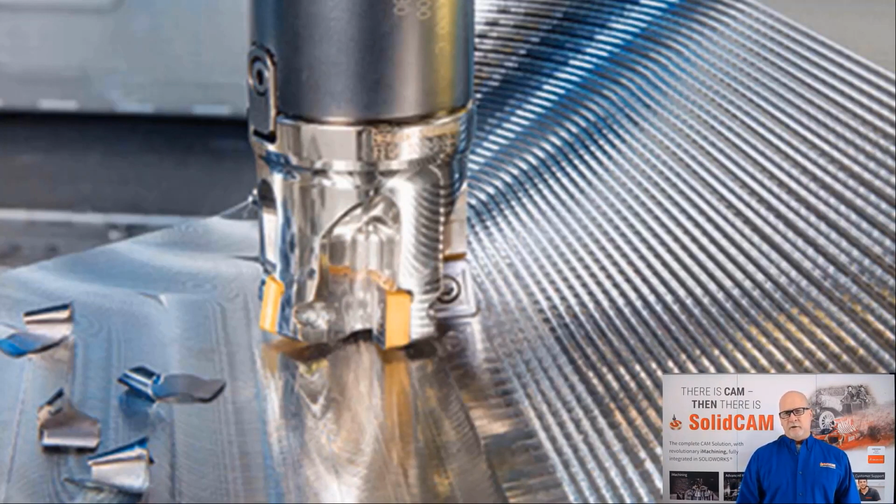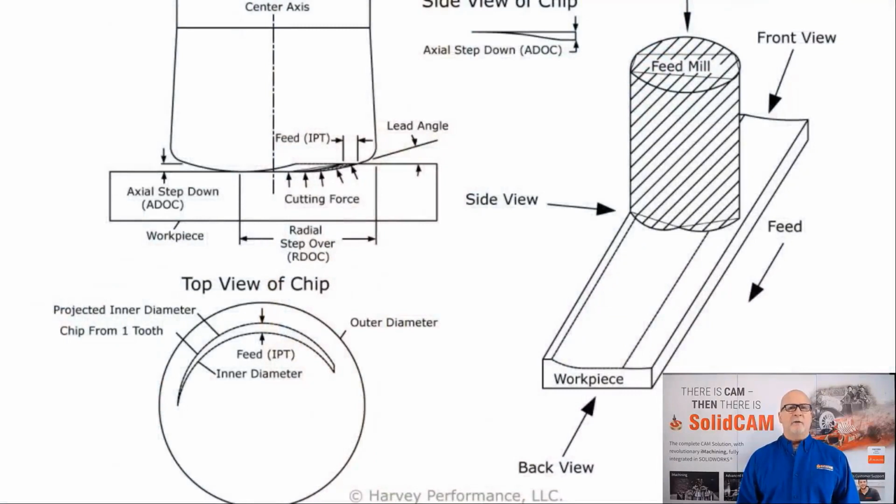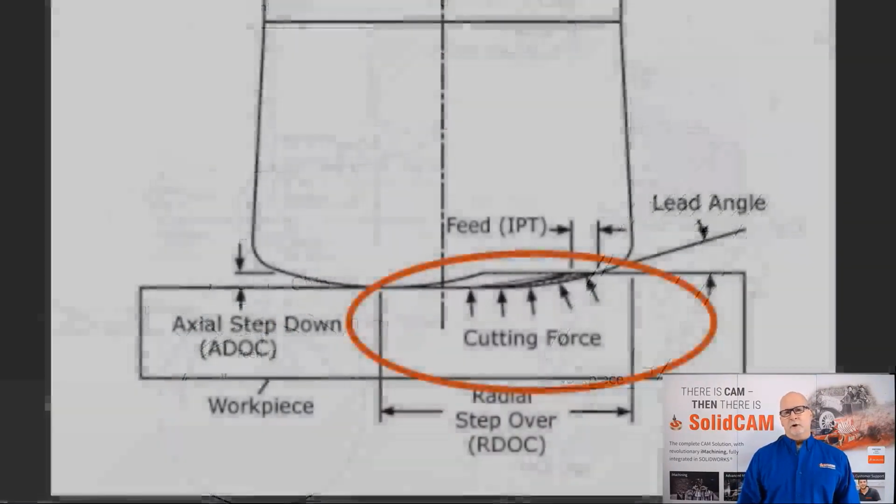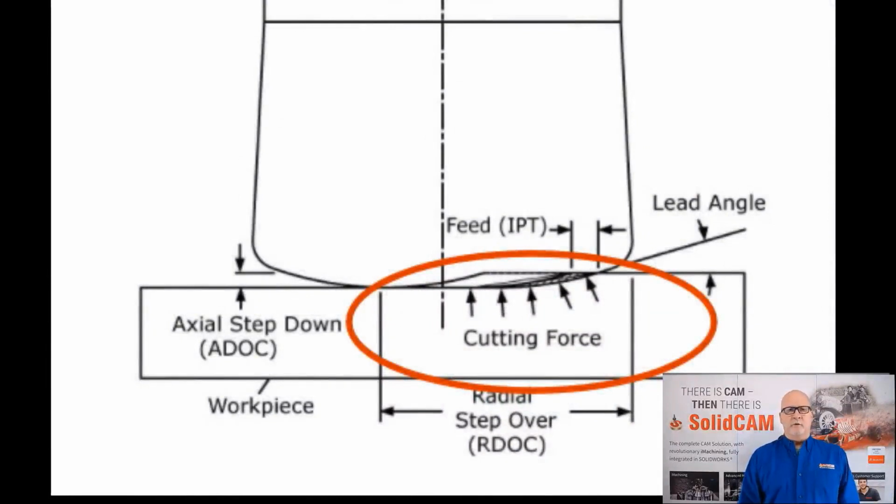As you can see in this image, the toolpath starts at the top and works its way down to the bottom with very shallow steps, clearing out the entire area at each step. Now these toolpaths are almost always performed with inserted cutters, similar to the one shown here. You'll notice in this image that the shallow axial depth of cut ensures that the force vector on the tool is directed in a more parallel direction to the tool axis. This is what allows for the higher spindle speed and feed rates.